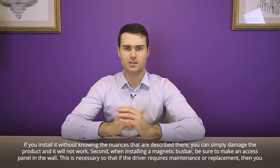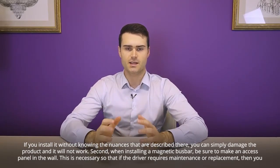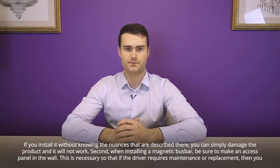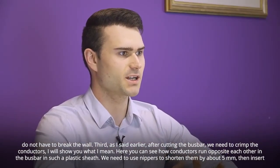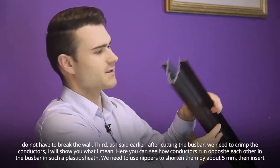Second, when installing a magnetic bus bar, be sure to make an access panel in the wall. This is necessary so that if the driver requires maintenance or replacement, then you do not have to break the wall. Third, as I said earlier, after cutting the bus bar, we need to crimp the conductors. I will show you what I mean.